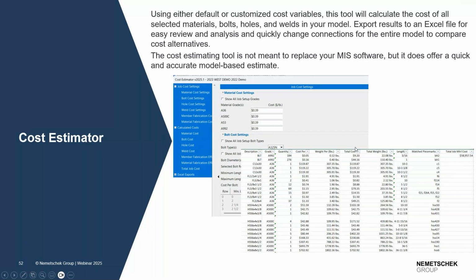It can also help you in the estimation process. So SDS, along with modeling, provides ST modeling also, that is plugged in. That's a standard format which is in the model only, in your license only. So you can just simply make a stick model, and you can take out your quantity takeoff. Along with that, you can use this cost estimator, and you can send it to your fabricator. So there will be high chances of winning the bid.